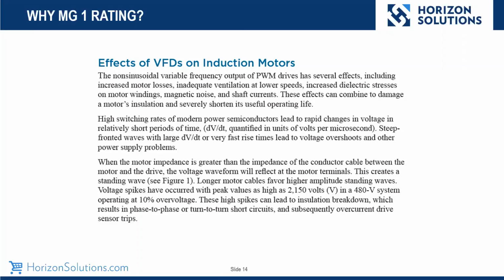One of the reasons is the high switching rates on these power transistors. The advent of the IGBT, insulated gate bipolar transistor, added a lot of shortened switch times, where the dV/dt was rather steep, where we had a huge change in voltage over a very, very short period of time. And this caused a lot of issues with steep fronted waves that would go down to the drives.